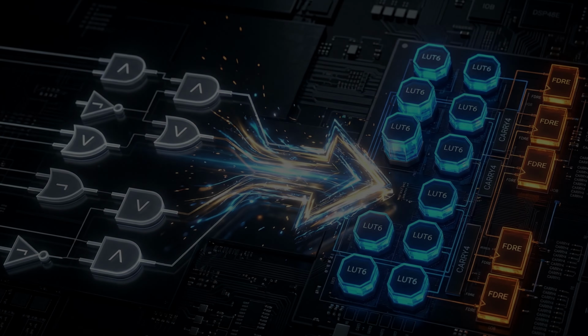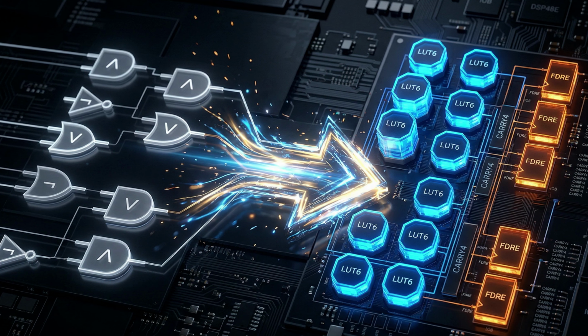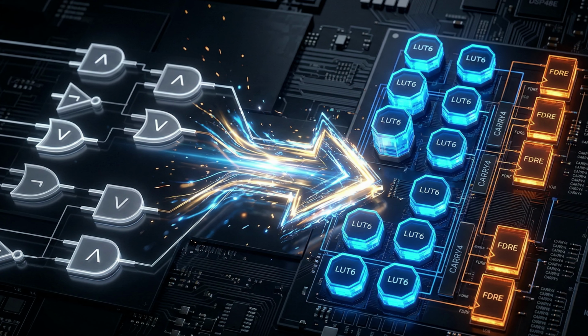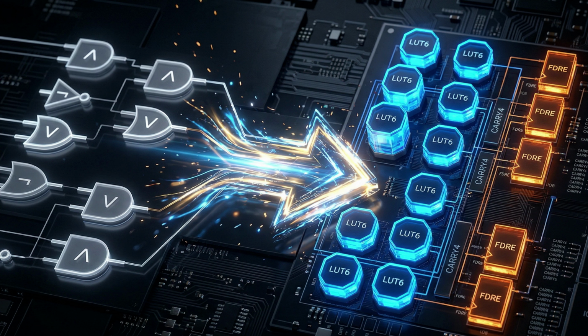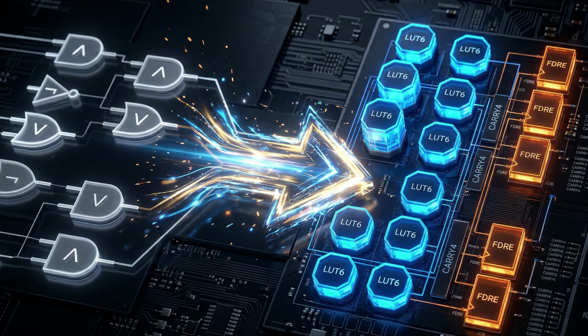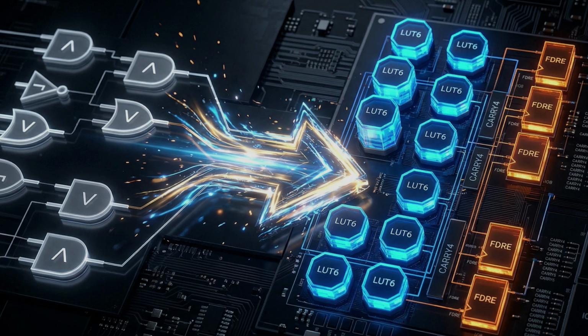Third stage, technology mapping. This is where abstraction ends. The optimized logic is mapped to real primitives in the target FPGA's library. For the Xilinx UltraScale Plus, these are LUT 6s, FDRE flip-flops, and carry 4 chains. Every abstract AND gate now becomes a real LUT configuration. The design is now written for this specific silicon.